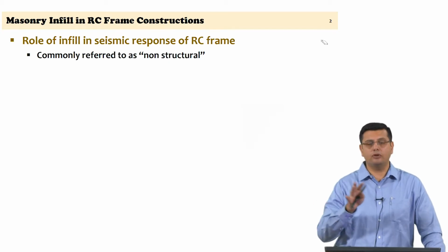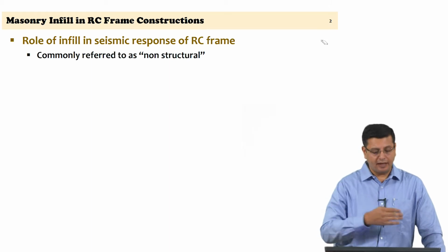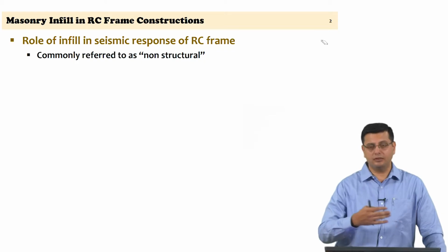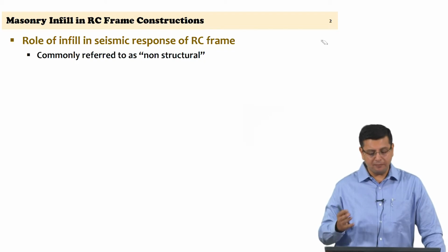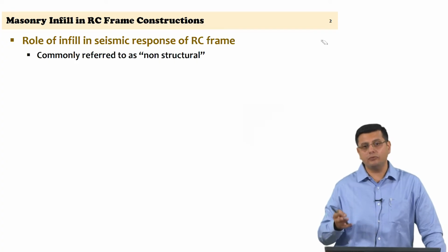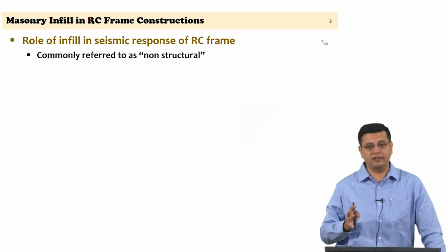That is, the mass of the infill panel is considered in the calculations of the seismic weight, and in the model this might be considered as a line load acting on the beams, but very rarely was this considered to be a structural part of the reinforced concrete frame.